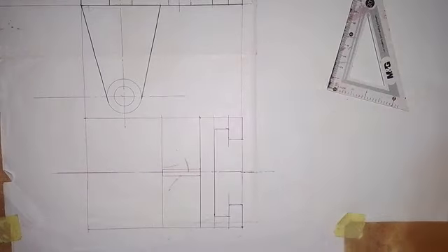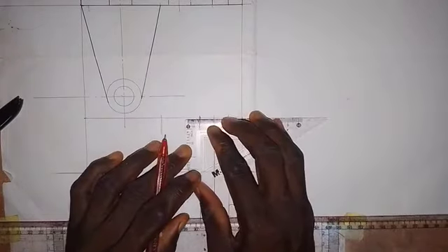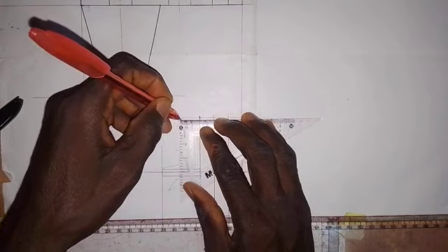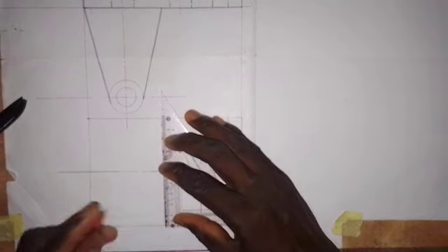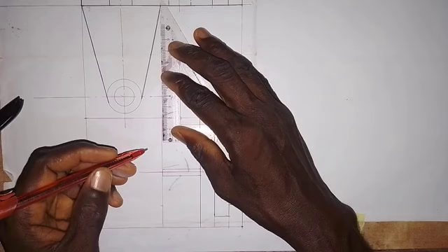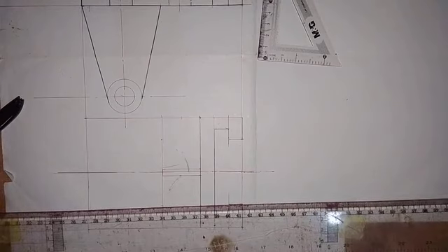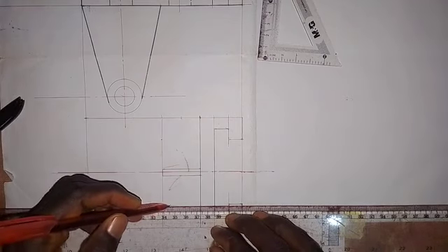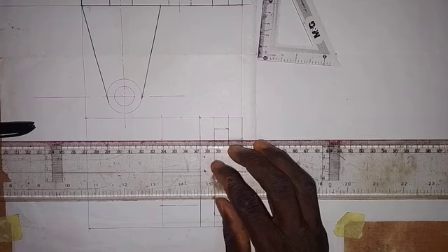Now let's draw the circles that we have here. So from this end here, we take 17 millimeters forward to locate the center of the circles. So 17 millimeters forward, this is 17 millimeters. And then from here we take 20 millimeters to this side. This is 20 millimeters, and I will also come to this end here. I will take 20 millimeters down. So this is 20 millimeters. So we are going to draw a horizontal center line here, from this point. So we draw a horizontal center line here for the circles. Okay, so we also draw a horizontal center line here.